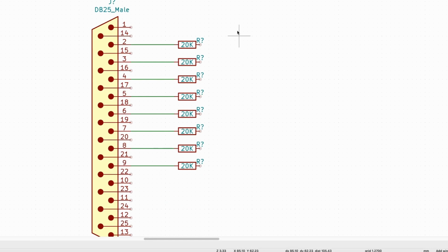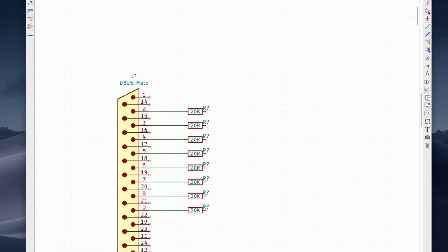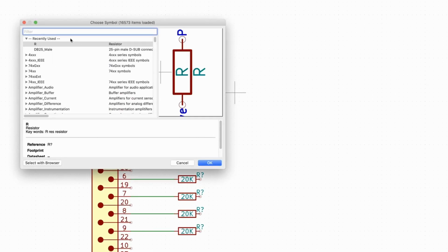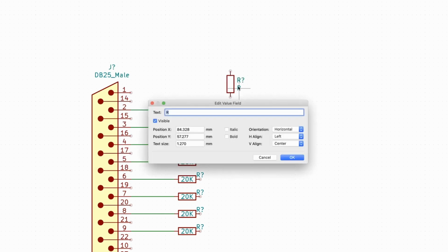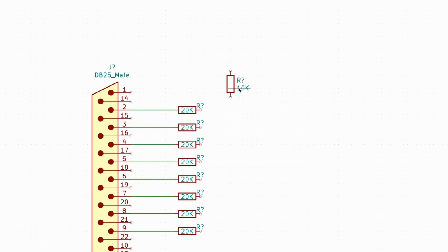So there we go. Now we need to add more resistors. So click there, click where I want it. I want an R, yes. And the value, V for value, this is 10k. And I again do the C to copy, and let's give it a bit more real estate.